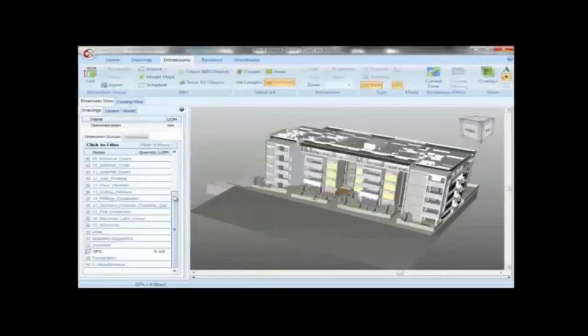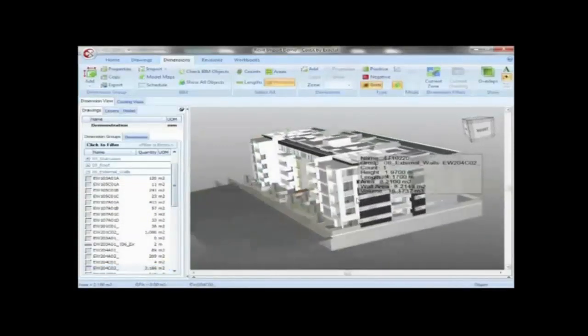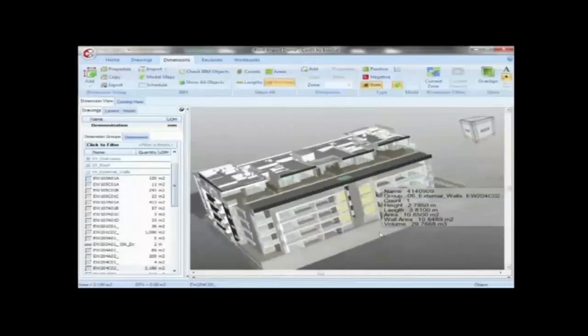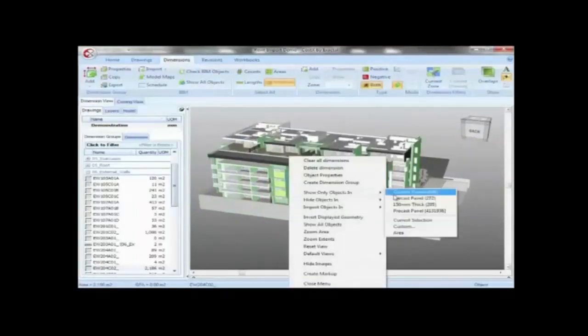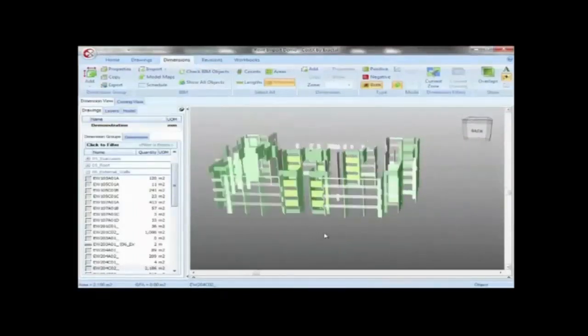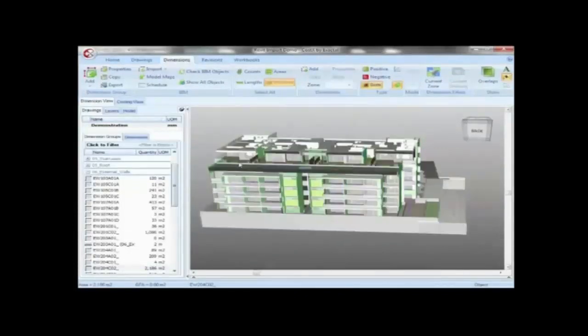The next thing is you'll start to see down the bottom left-hand side of the screen information being imported. So we've not measured anything. The same codes are coming into the model in terms of the elemental codes. We're now getting the quantity of the precast panels, which is 2,186 square metres. The next phase is we bring in our template. So we bring in a template and we start linking it to costs. And what we get is a first cut of the design like that. So we get an estimate in moments. The shift is, this is just a first cut, so it's now what you do with that information.